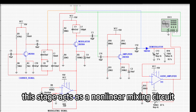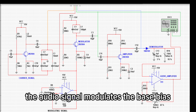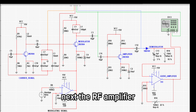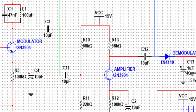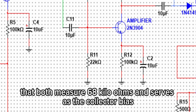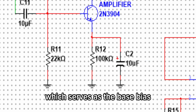This stage acts as a nonlinear mixing circuit where the carrier is applied to the collector. The audio signal modulates the base bias and the output becomes an amplitude modulated signal. Next, the RF amplifier, where the modulated signal is then passed through a Class A RF amplifier using a 2N3904 transistor. Key components include R10 and R13 that both measure 68 kiloohms and serve as the collector bias. Next is the R11 that measures 22 kiloohms, which serves as the base bias.